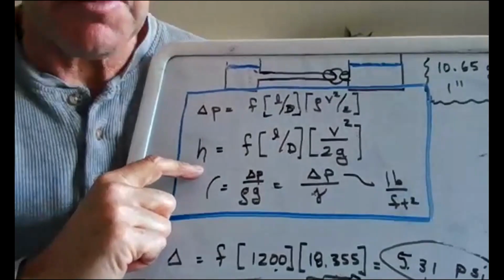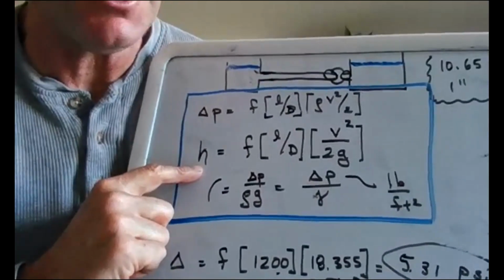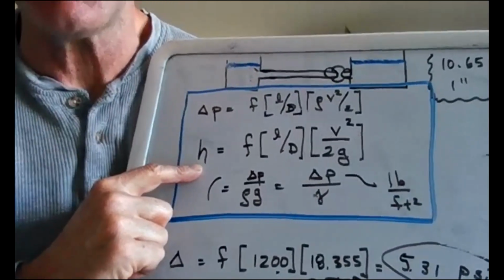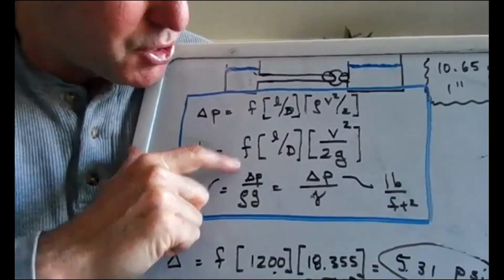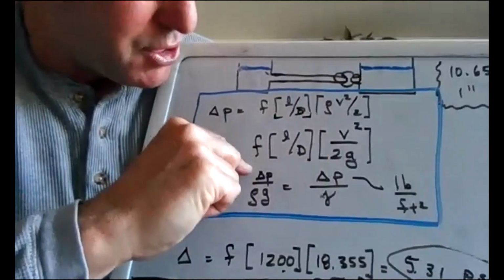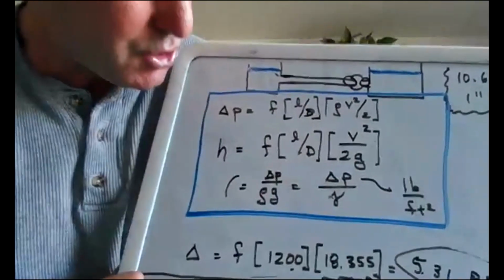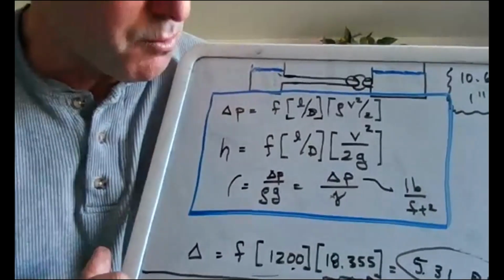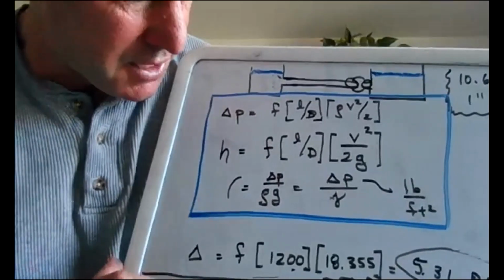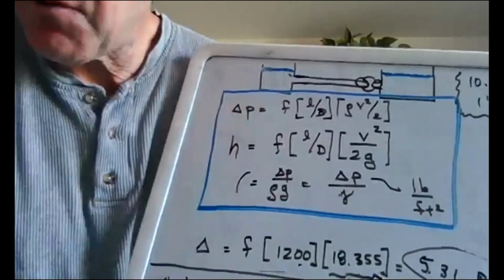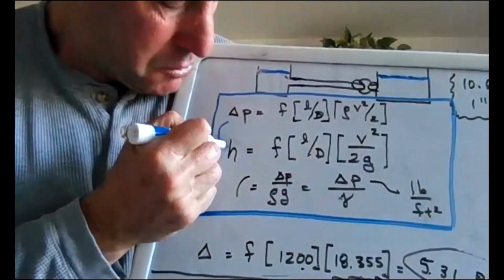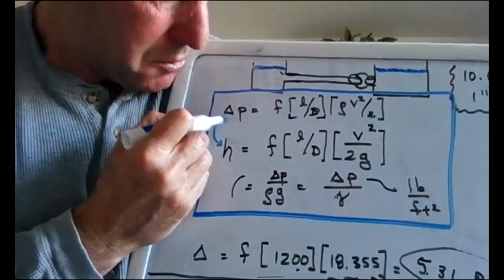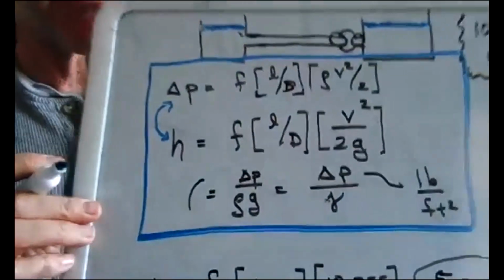If we want to figure out the pressure drop in terms of feet of water, say feet of H2O, well, one way we can get it is just get rid of the rho and divide by g. And so there's my equivalent relationship. But it's also helpful to remind ourselves how we go from this formula right here to the h formula right there, or the other way around.